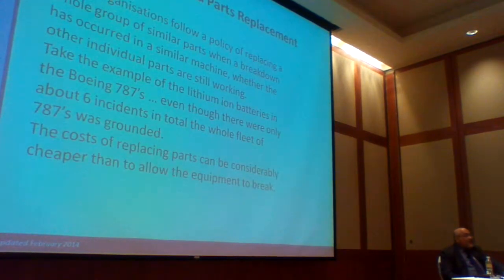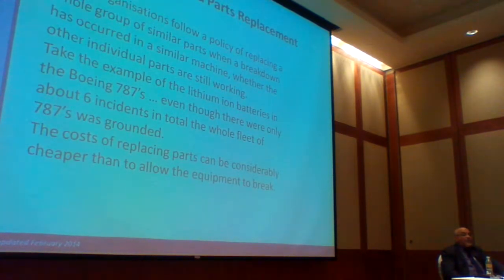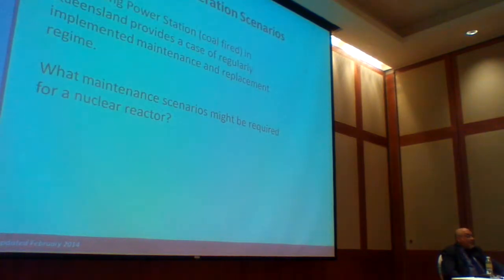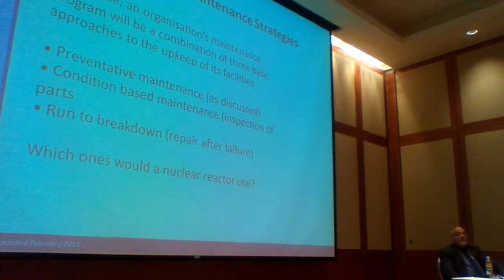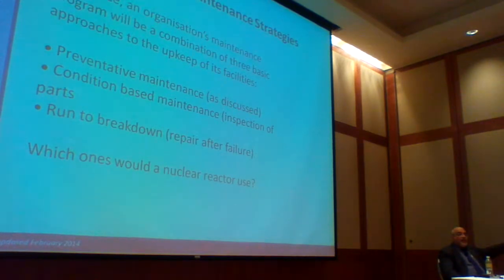Okay? Equipment and spare parts. For parts replacement, you need to have all spare parts related to the critical equipment available in your stores. You can combine maintenance strategies like preventive maintenance and condition-based maintenance. Condition-based maintenance is about judging the condition of the different equipment or assets. If there are civil assets, then you'll be looking at the cracks and the scaling and these things, and you will know what condition they are in. And accordingly, you can apply the different services or maintenance programs.